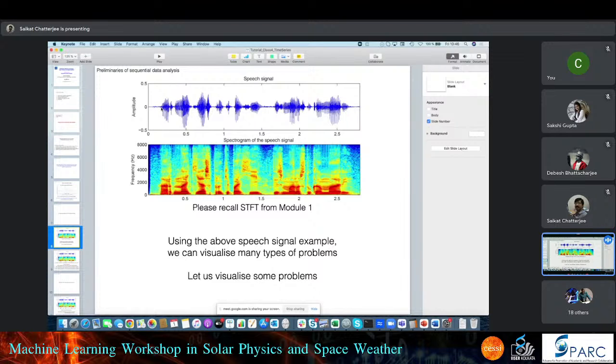These windows are shifted, and for every window you compute the power spectrum. The amplitude is with respect to frequency, and it is plotted in the z direction, perpendicular to your computer screen. More red means higher amplitude of the frequencies, and blue means low amplitude.